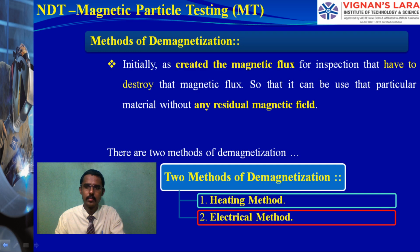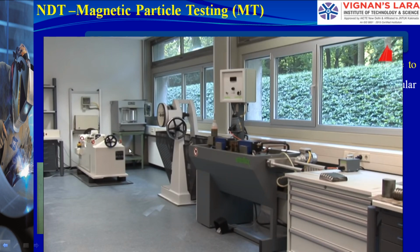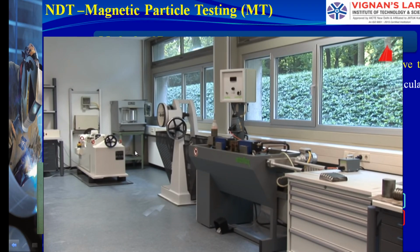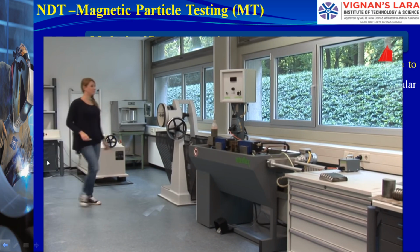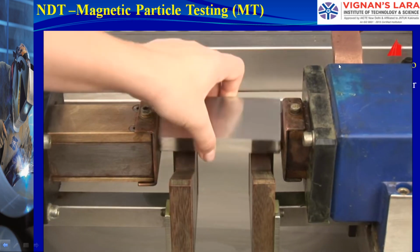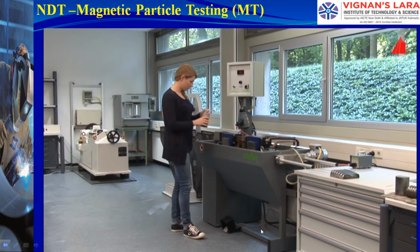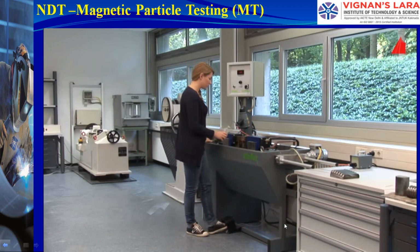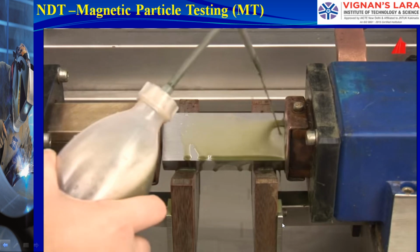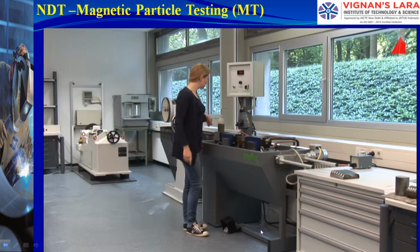Non-destructive testing, magnetic particle inspection. The magnetic particle examination is an excellent method to investigate near-surface defects in ferromagnetic material. This video shows the basic principle and the practical procedure. The material tester gets the machine ready for use and inserts the test lead between the two poles of an electromagnet. Then she takes a bottle with a suspension of magnetic particles, turns on the electromagnet with a foot switch, and applies the suspension of magnetic particles onto the test piece.